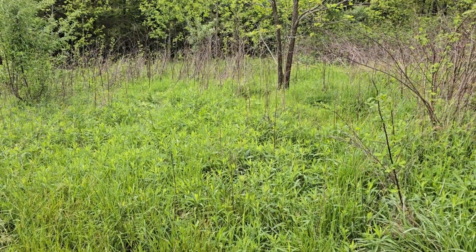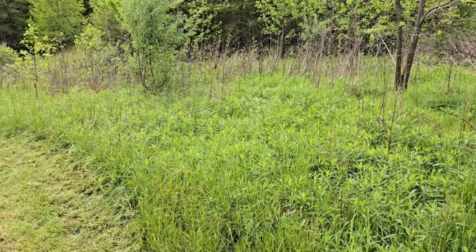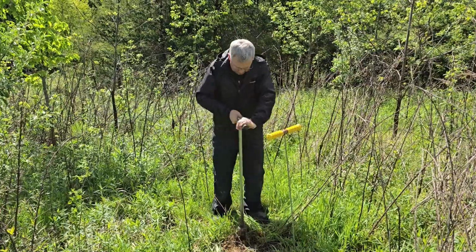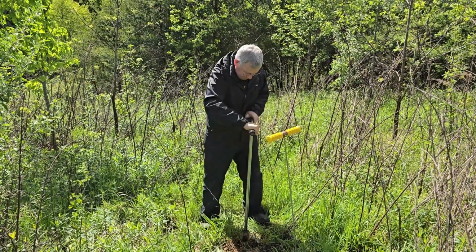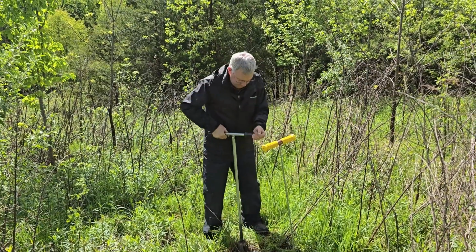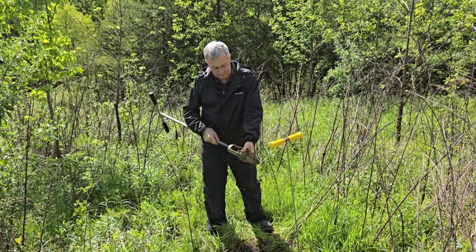I located an open area on high ground near the dam where the clay soil needed to repair the dam could be obtained. The soil test hole I dug with an auger in the open area showed that there was clay approximately 10 inches below the surface in a layer about 3 feet thick. There would be a large enough quantity of soil to repair the dam.